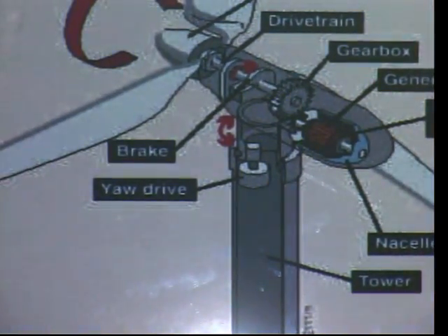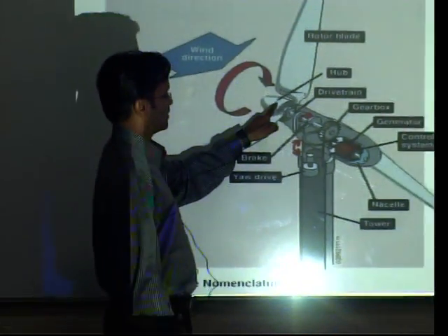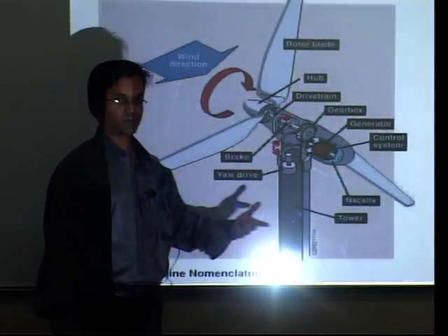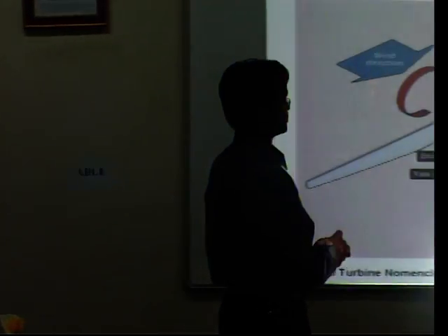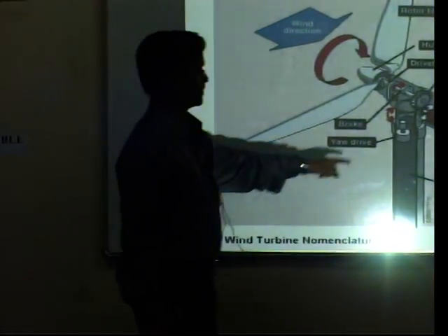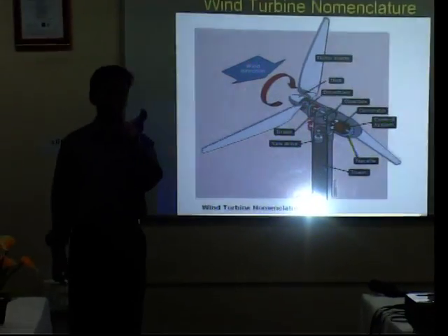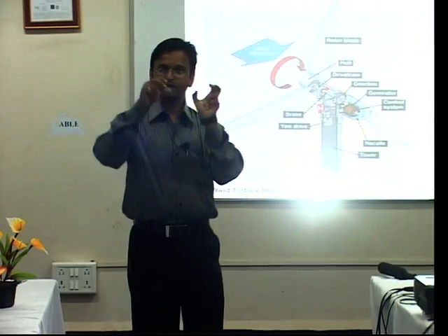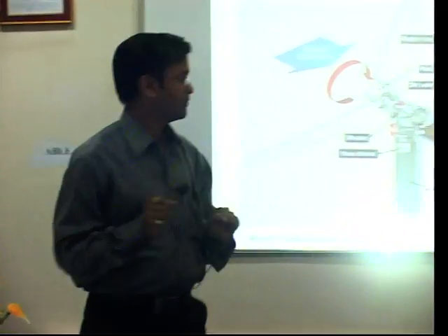This speed is 5 to 7 meters per second, and at this lowest speed electricity cannot be generated. That's why the gearbox is maintained, and the multiplication gear is connected to this. The gear mechanism is again classified into 2 groups: first is helical, and next is bevel gear, with a ratio of 1:40 or 1:67.